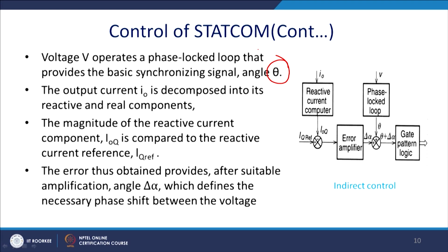The output current is decomposed into two components, real and reactive components. The magnitude of the reactive component I0q is compared with the reactive component of the IQ reference. The error thus obtained provides, with suitable amplification, the angle.